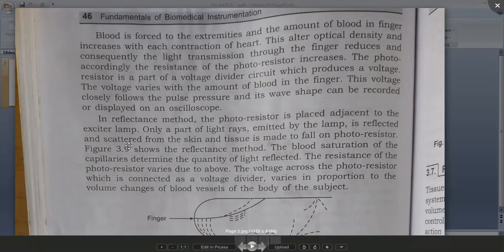So the pressure variations, how the pressure is changing. If more pressure is coming, how the heart is pumping the blood can be understood by the doctor. That continuous measurement of the pulses of the blood pressure will be recorded and displayed on an oscilloscope. We can also observe on the oscilloscope, by connecting the variation of the output voltage to it, how the pulses are produced, and those pulses represent the variation of the blood pressure in the blood vessels of the body.